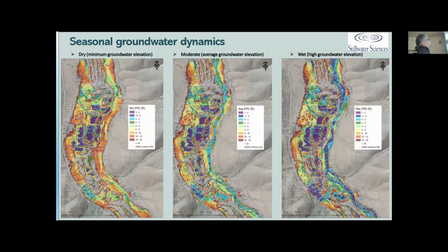And that data allowed, and these are some exhibits from Stillwater Sciences that they put together, that's fundamentally showing the hydraulic gradients, or the differences in water surface elevation, in the tailings reach during various environmental conditions. And these are really critical for helping us understand how the water is functioning in this highly modified system. So when we decide that we want to come in and create some habitat, like we did with that Sugar Creek refugia habitat, we don't go and make things worse, fundamentally.